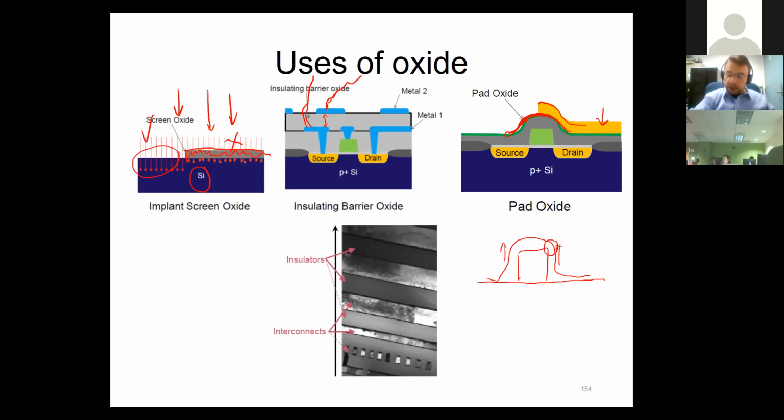You see, this is really a huge slope here. It might break and it might create stress on the side walls, and that might actually put a lot of tension on that little thin layer there. But if you, on the other hand, put a thin layer of a pad oxide to smooth out those regions, it's going to be, of course, better than this first example. So it won't really see those kinds of sharp corners.